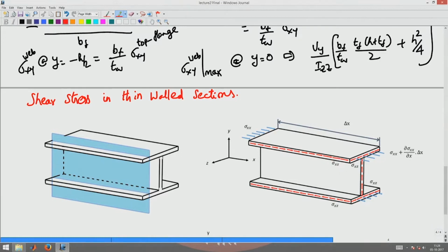Now, to compute this shear stress, the expression remains the same, it is Vq by Ib, except that now the b would be the thickness of this flange. Okay. And your area that you have to consider should be taken from this end to the section point where you are interested in finding the shear stress. Okay. So, you have to take the entire flange thickness area rather than sectioning the flange along a plane which is cut parallel to the xz plane.